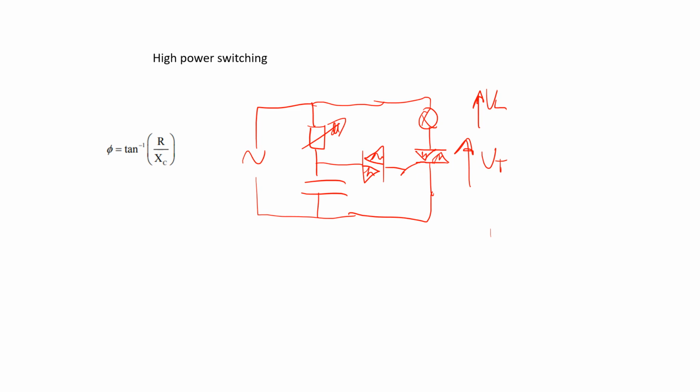And if it's just using the thyristor, it will usually be a graph, and it's just using circuit rules. When a thyristor is on, you need to say what the voltage is. When you unlatch it by using capacitor commutation, it drops down by whatever the power supply is, the same amount as when you press the switch. So it's just circuit rules and voltage arrows, and maybe filling out a table. But this one is hopefully straightforward, with the actual graph there.